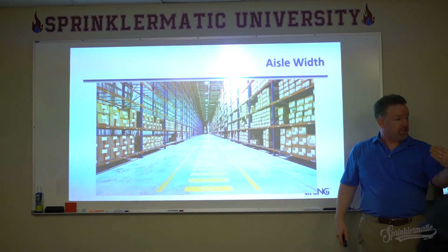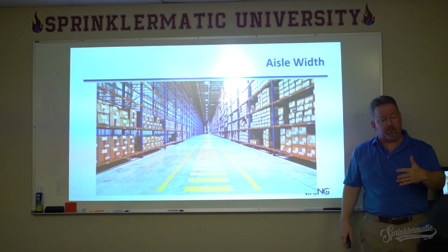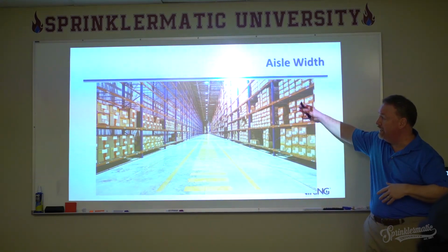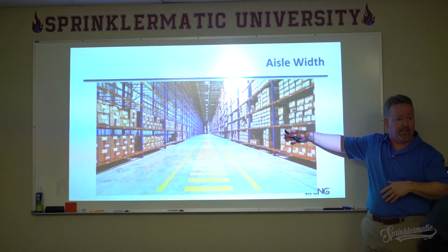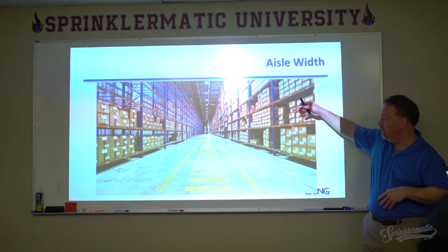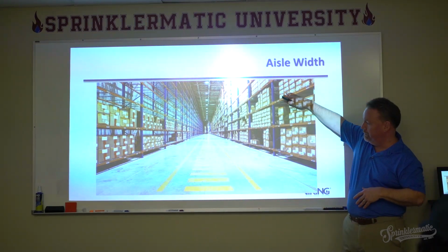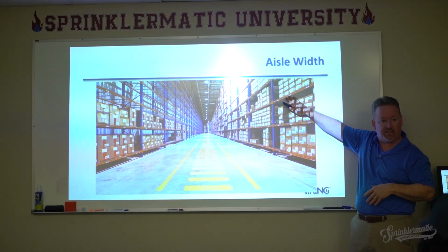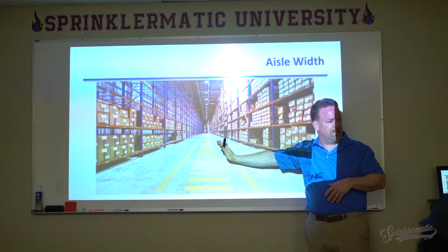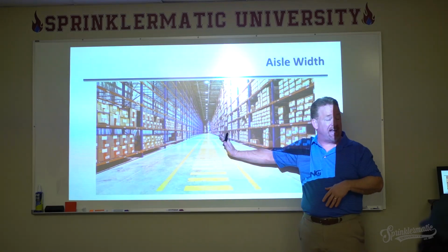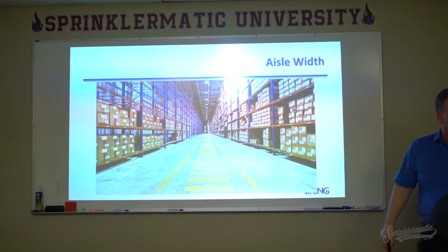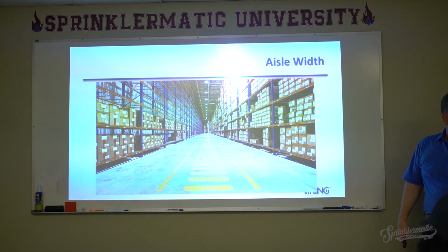That's actually one of the success or failure criteria of a sprinkler system's test when we're designing or testing sprinklers to protect rack storage. We have what we call the commodity that's being tested, and then right over here we've got what we call the test array. And one of the things is you cannot let the test array, the exposure, catch on fire, or you fail the test. If it jumps the aisle, you're done. Test failed. Okay?